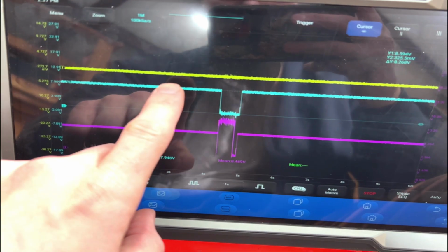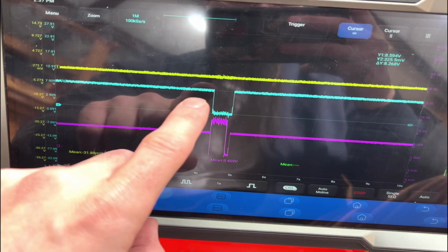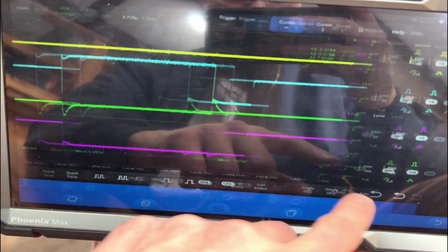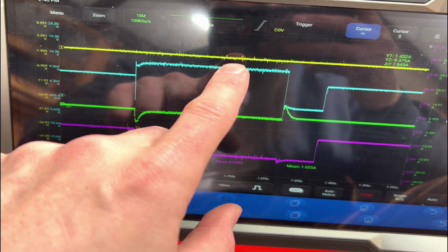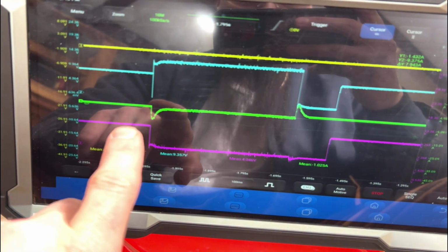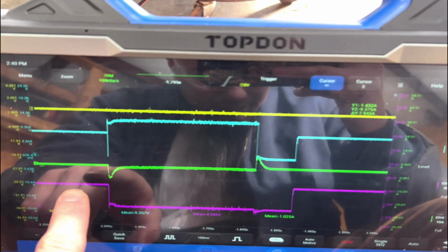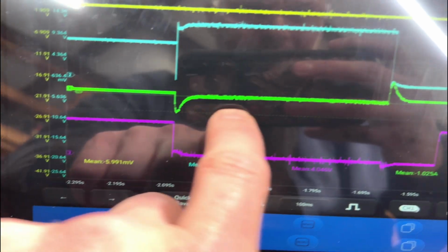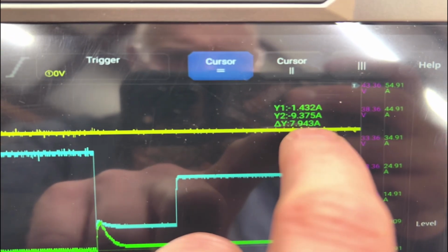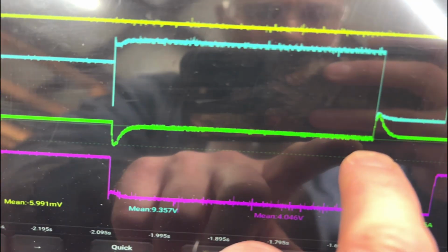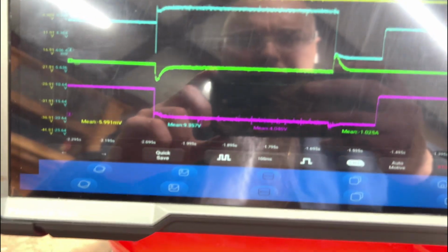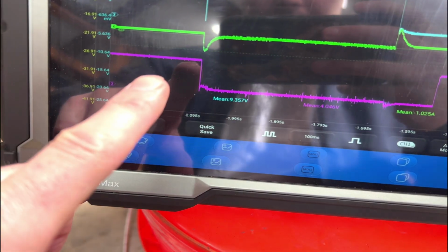These are screenshots. So last time going into 4, we had a blue low and a purple high. Next one is the inverse. So we go from our 8 to essentially 12, and then we go from whatever it was, 8 to 0. And we are getting some current flow. We have a peak of about 9 amps, and then it's flowing a constant 1 amp across it. So we are getting some current flow. That is not an open circuit by any stretch of the imagination.